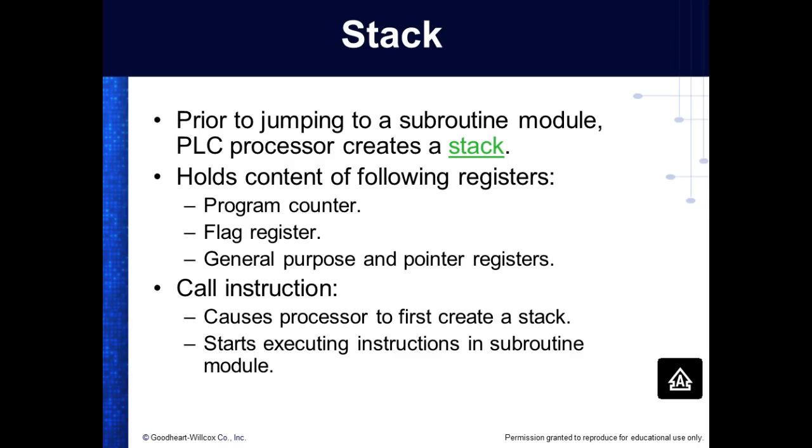It pushes the contents of the following registers. It saves your program counter, changes your flag register, and any general purpose registers or pointers. Then we call the subroutine, which I'll call the JSR, that's just the way I learned it. It causes the processor to start executing instructions in the subroutine, and how does it know where to come back to? Return. The stack is already there, right?